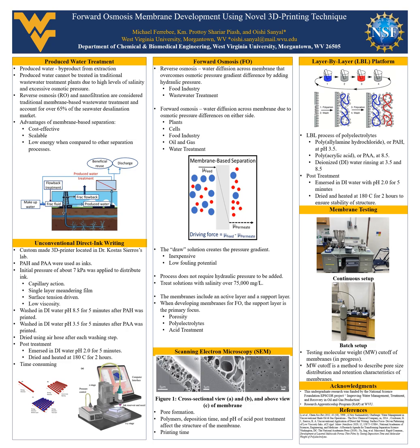SEM images, like Figure 1, of the top and cross sections of membranes were found. The pores present in image C are formed by rejected water by the membrane. The interconnectivity is seen in the cross-sectional images, both A and B. It is formed by positive charge of the amine group by acid treatment, then the charge repulsion in the polymers. The structure is then stabilized after the heating step of the post-treatment.